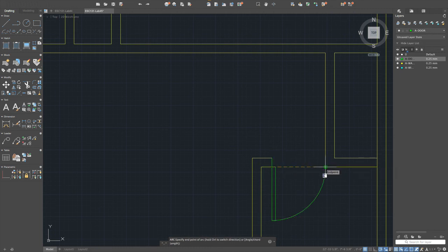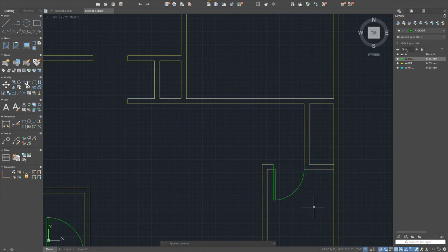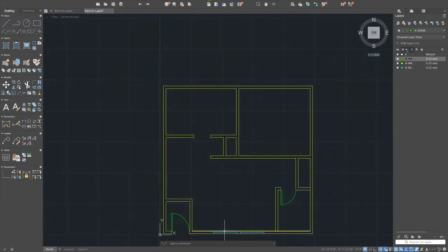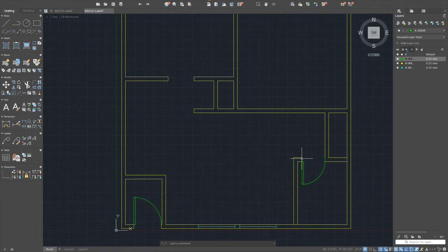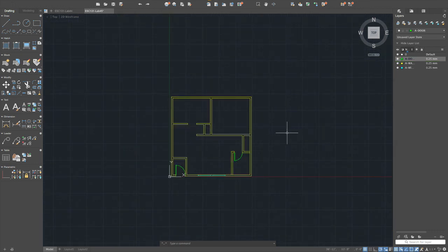Okay, in this case I didn't need to press the control key because my arc is running counterclockwise from the start point. There I have. It's a very common practice in engineering, when you run things in the counterclockwise direction, mostly they are positive, right? Torque and so on and so forth. That's why AutoCAD also follows, when you trace an angle in the counterclockwise direction, it keeps it as positive. But if you are tracing it in the clockwise direction, then it's negative. Okay, so that's pretty much it.